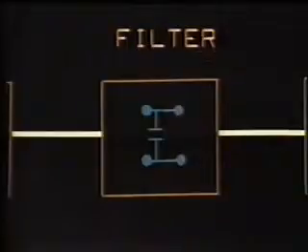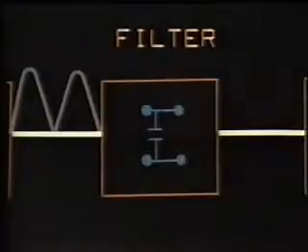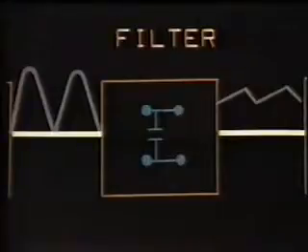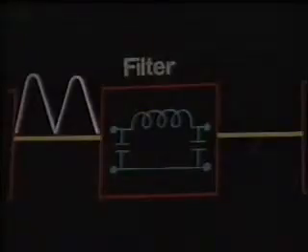The pulsating DC is passed through a filter circuit which smooths out the variations or ripple. Filter can eliminate most of the ripple but not all. With a simple filter as is shown here, the ripple left in the final DC voltage can be considerable. A better filter is needed to minimize the ripple in the output DC voltage. Graphically, such a voltage can be represented by a straight line.